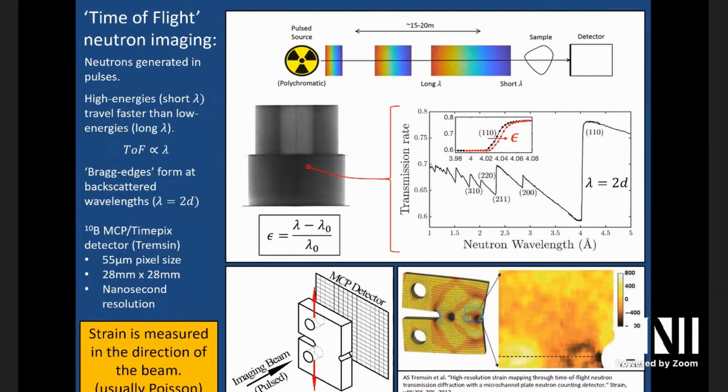Right? Exactly, yeah. So there's something not really made clear mathematically: the strain has to be relatively smooth on the scale where you've got lots of crystals. Yes, as in the size of crystals is way smaller than the beam dimensions. Right, and the strain is averaging over that beam anyway. So the other measurement techniques have exactly the same problem. If the size of your gauge volume is getting close to the size of crystals, then everything starts breaking down and you can't do good measurement. So that's an assumption we're always going to make.